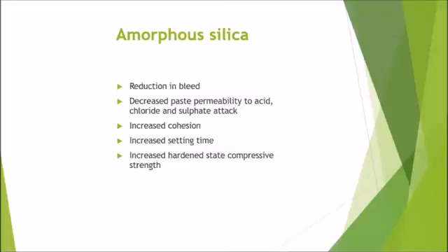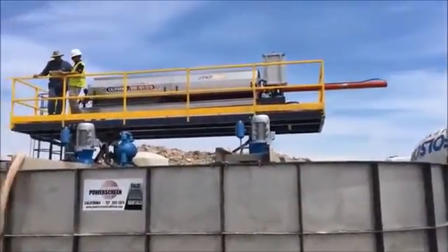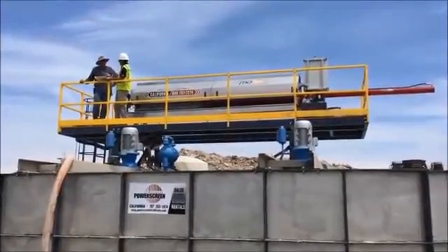The properties changed by the inclusion of these SCMs can give a concrete blend both advantages and disadvantages over general purpose Portland cement. Their use, however, is increasing due to their technical, environmental, and in many cases economic benefits. Beyond this, fly ash and slag can also reduce the costs of production, while amorphous silica can cost significantly more than just ordinary Portland cement.